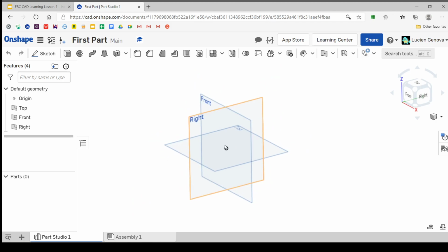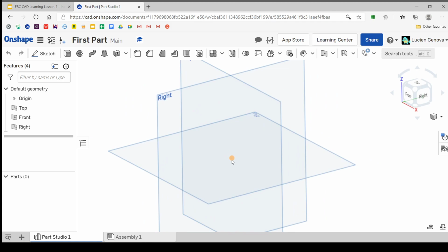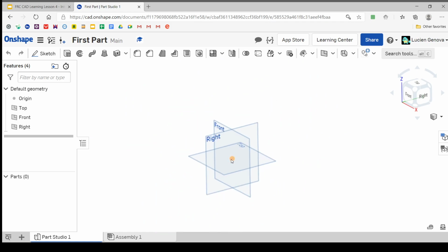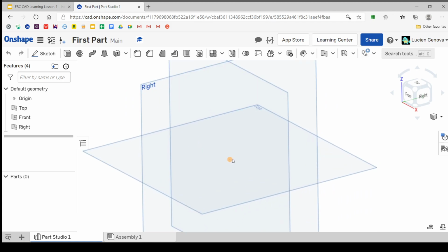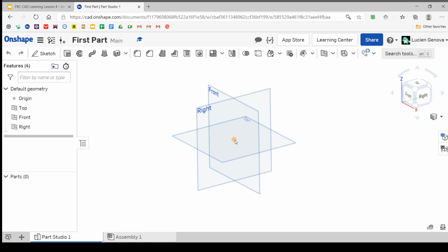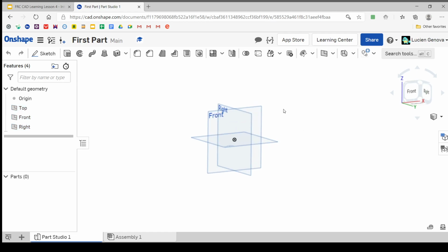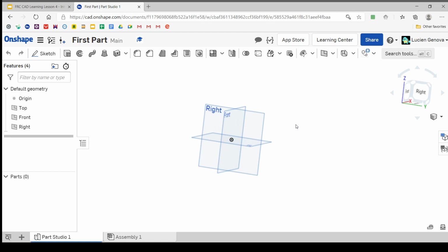And then you can also zoom in, or zoom out. I actually have my scroll wheel flipped to mirror SolidWorks, but really, it doesn't matter. So you can zoom out, and you can zoom in like this, right? And then you can also left-click to select. You can select multiple things without having to press any sort of control, right? Left-click to select, and then click the background to deselect, or press Escape.